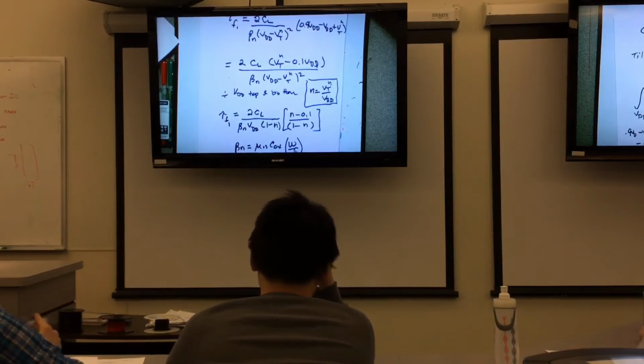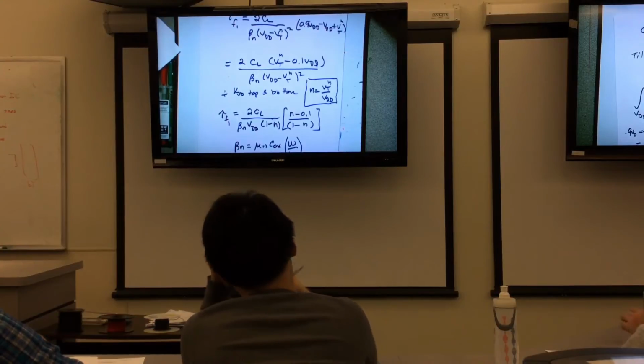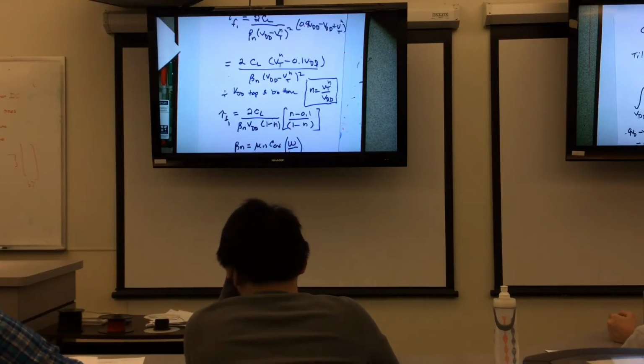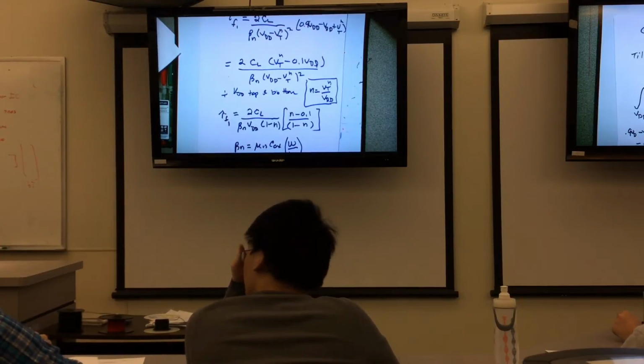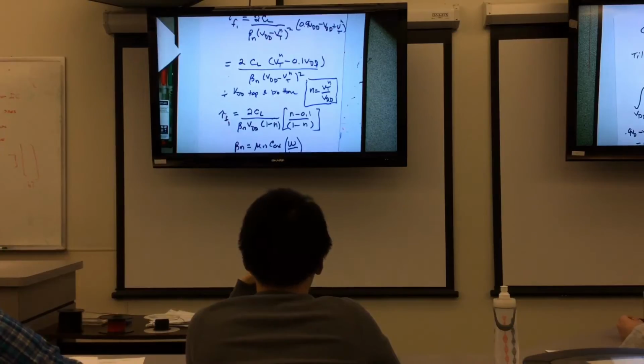And it says the wider I make the driver, but in this case the sink, the faster I can discharge the charge. So if I wanted to think of this as a kind of quasi-resistor, then the resistance in the circuit is going down. Make it wider, it's less resistance. Same thing with the resistor. Okay, and that'll speed things up. And there's a few other things you can think about.